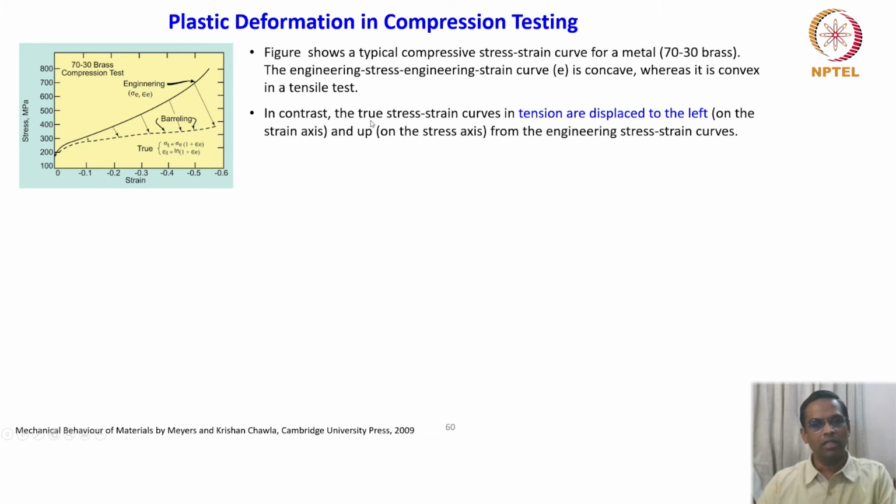In contrast, the true stress and true strain curves in tension are displaced to the left on the strain axis and up on the stress axis from the engineering stress strain curves. So you can see that when you take the true stress true strain curve from the engineering stress strain curve, it looks very different here.